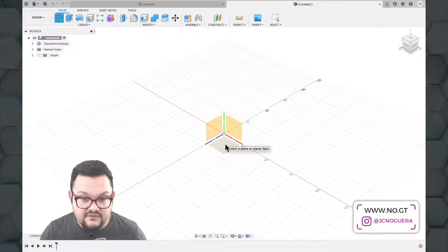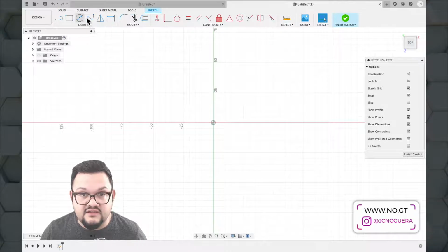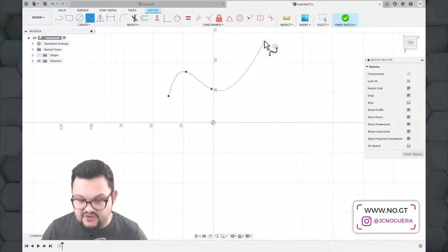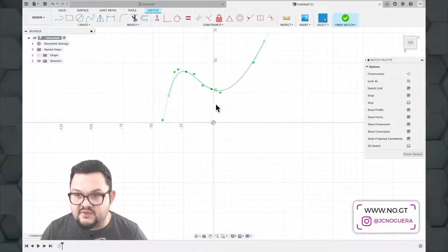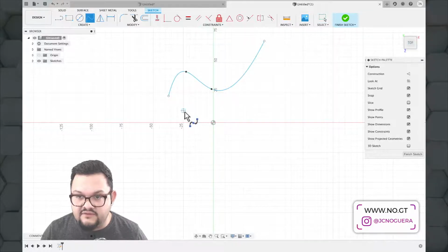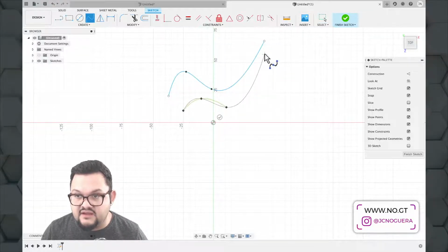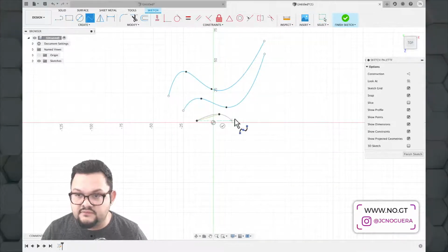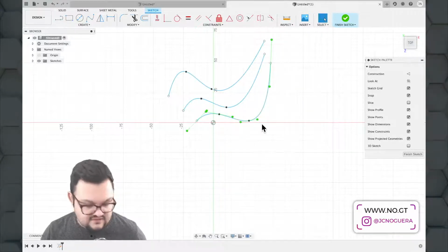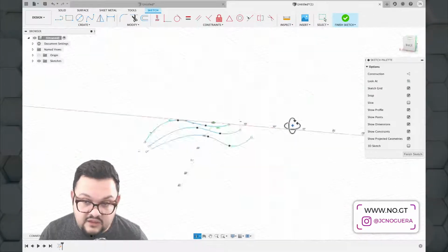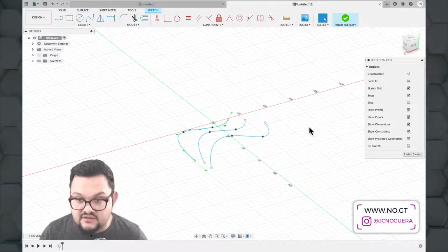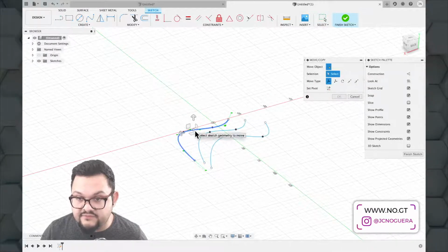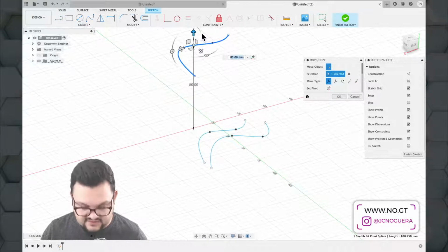So let's say I wanted to create a very complex surface. I can actually do that in a very controlled way. You can, of course, create different profiles that represent different parts of your object. I can, for example, create a set of splines here. And these splines can all have different varied geometry, varied curvature. I'm going to repeat this operation. These could represent all different sections of an object. This could be closed boundaries, or they could be open boundaries, just like this open spline. I can move these objects around in 3D space as long as they're not constrained to each other.